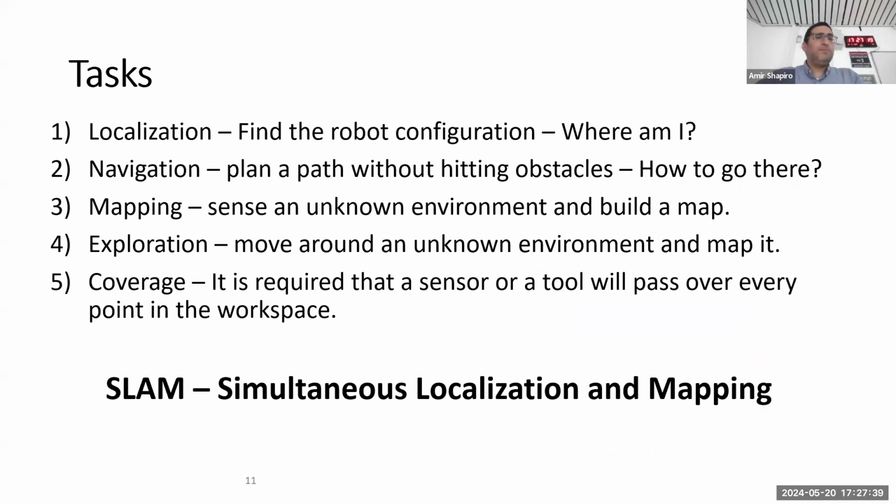We may have a few different tasks for robotics. One is localization, to know where the robot is, for the robot to find its own position. It can be divided into two sub-problems. One is when I know where the robot starts and I want to know where it went. The other problem is the kidnapped robot problem.